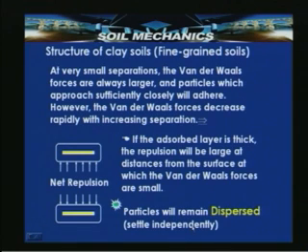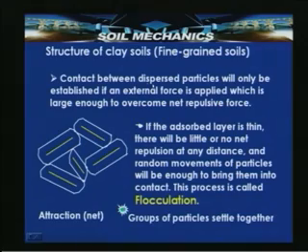When the net force is repulsion, that means that when repulsive forces overcome the van der Waals forces of attraction, it results in a dispersed state. Particles will remain in a dispersed state and they settle independently without coming in contact with each other. However, contact between the dispersed particles can be established if an external force is applied which is large enough to overcome the net repulsive forces.